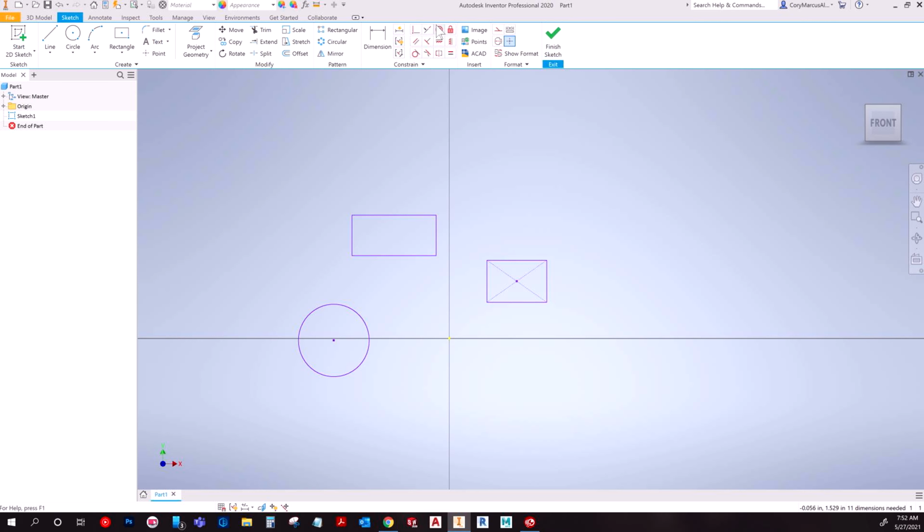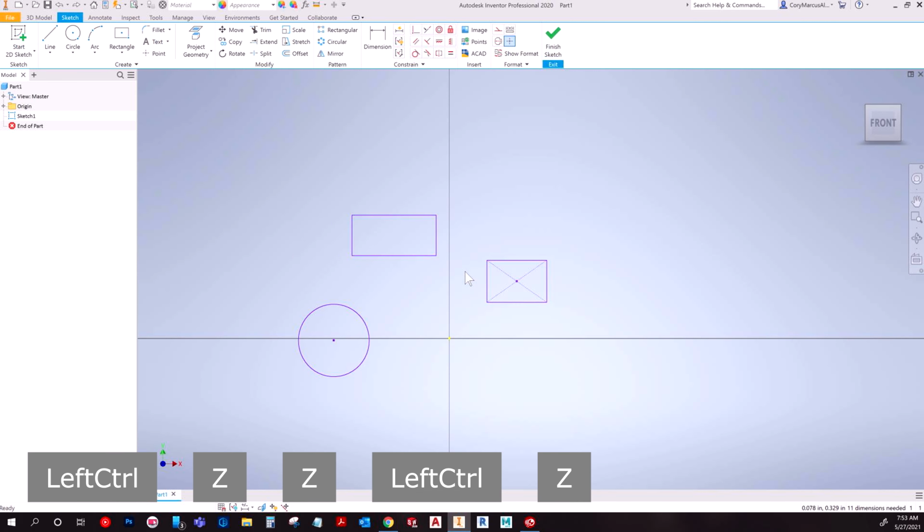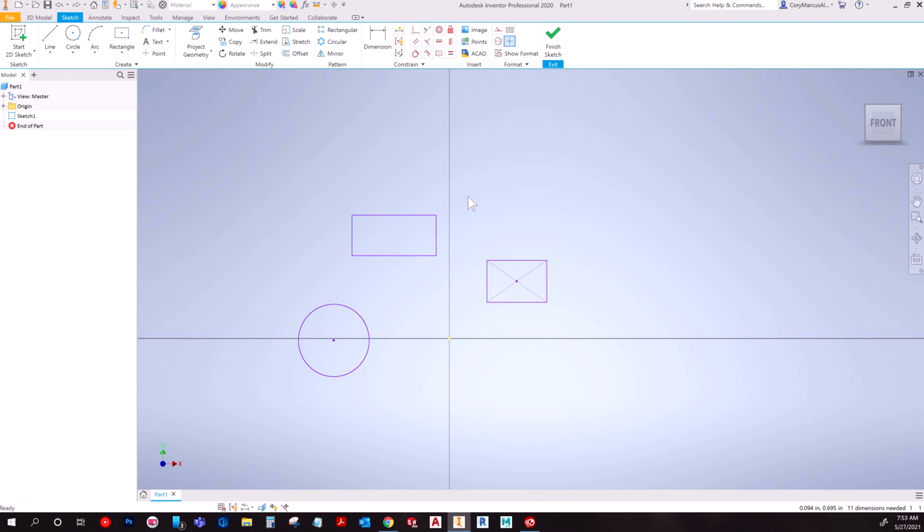So then we talked about coincident. Obviously I mentioned you can do a point to a point. You can also do a line to a point, stuff like that, and then you can just keep doing it as many times as you need. I can even do, as you see, the end point to a circle. Basically you're just saying 2 points touch. And technically you can do a point in a line or a point in a circle.